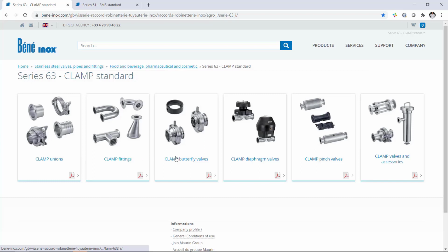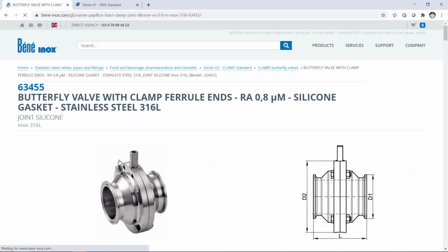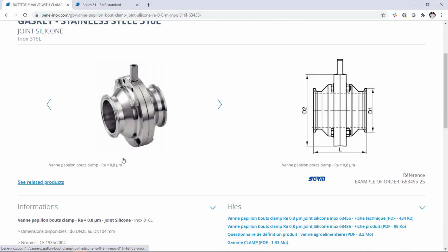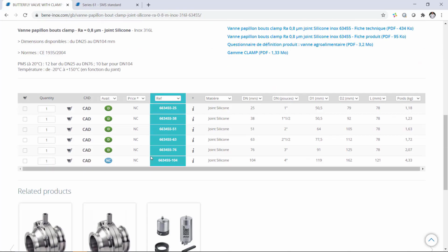You also have the option to search in the supplier portal, and many suppliers do provide the 3D CAD parts with product specifications which can be downloaded. You can pick the right part family member based on the requirement to download, view the properties associated to it, and later open in Solid Edge for adding the coordinate system information.